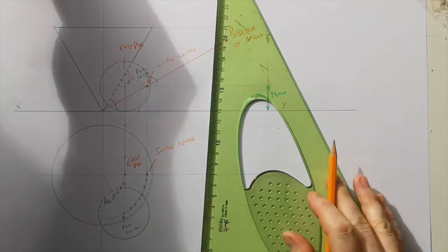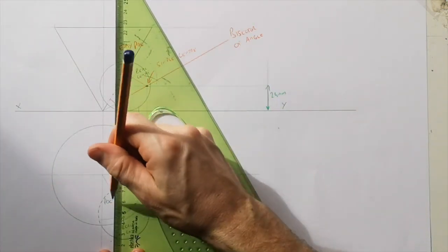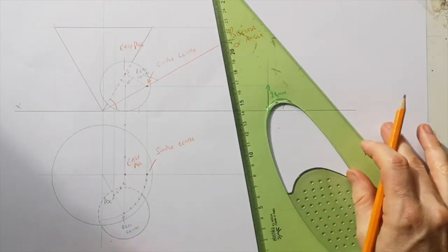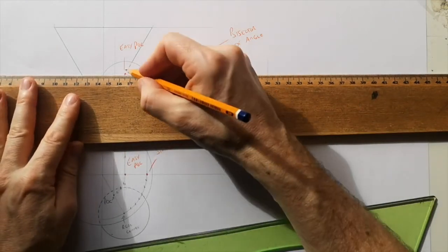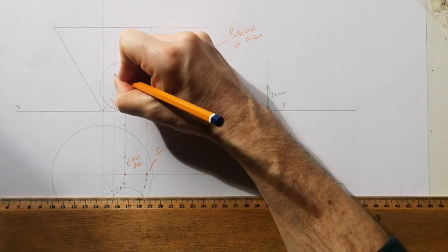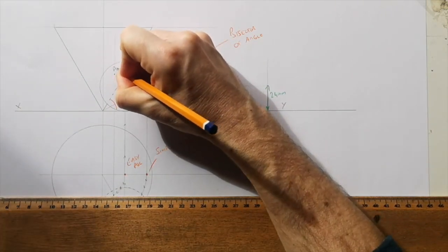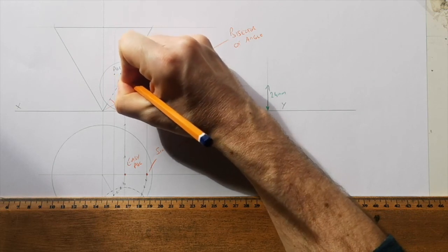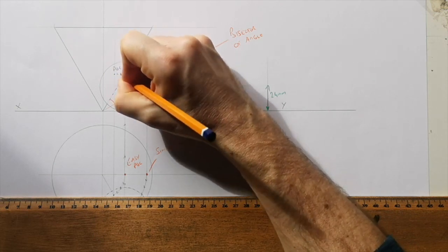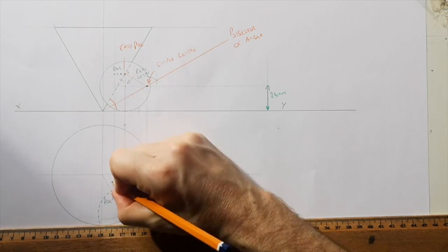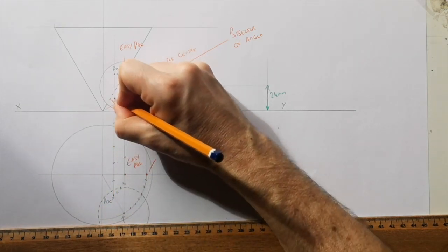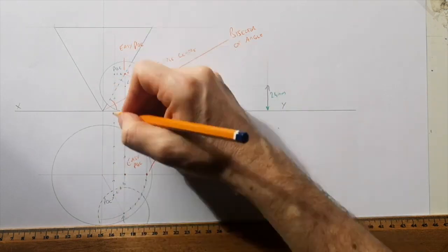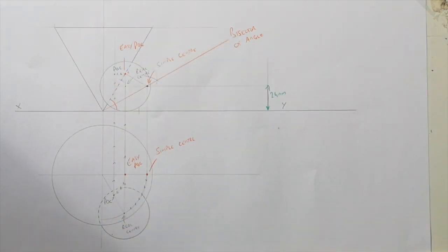I have it here, so I can project it up. Now we're nearly there. Remember, as it rolled around, it did stay at the same height. So we just come across from here, and there is my point of contact. So across from the easy one, because remember as it's rolling across, it just goes over there, and up, up, up, from where it is in plan. Because everything in plan and elevation can project up and down. There you have it.